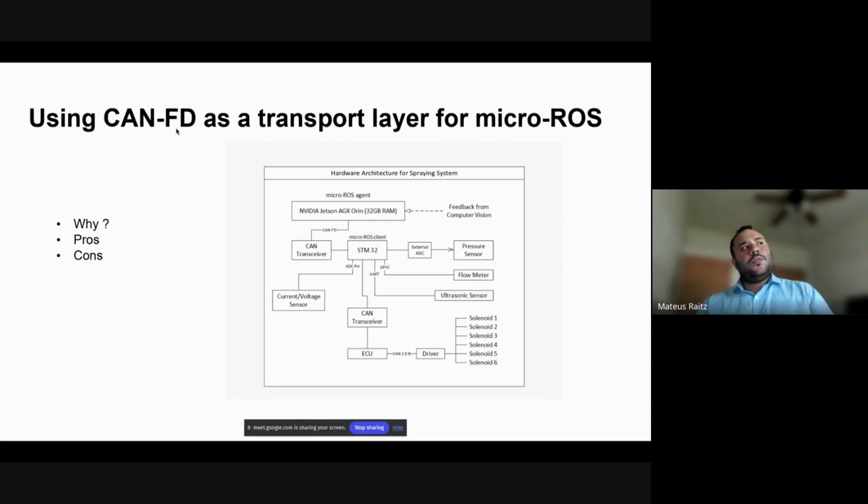I want to push that to the micro-ROS Zephyr module repo, but since micro-ROS only officially supports Zephyr 3.1 and I'm using Zephyr 3.5, the CAN API is different, so I need to make it backwards compatible with Zephyr 3.1 before I can push that.